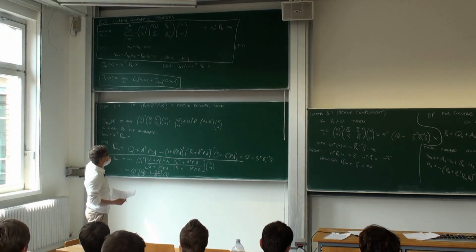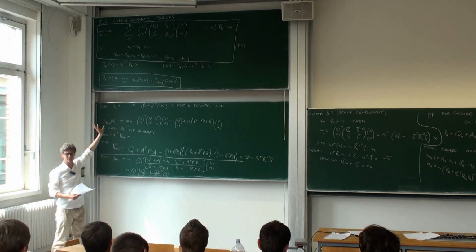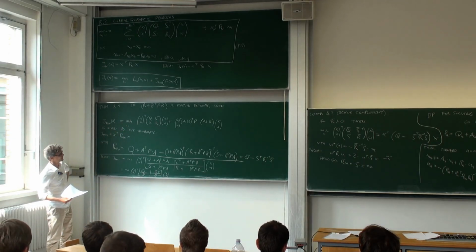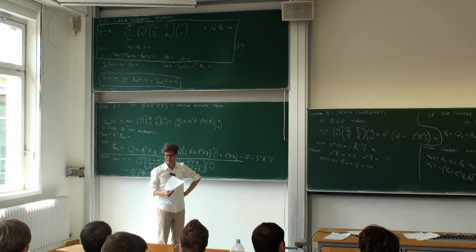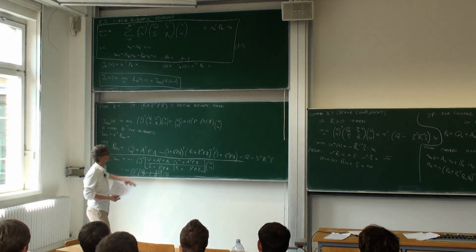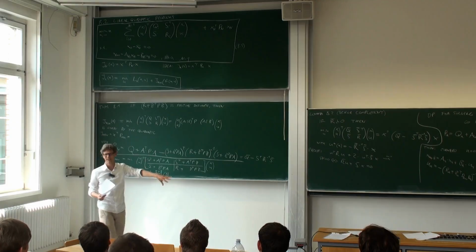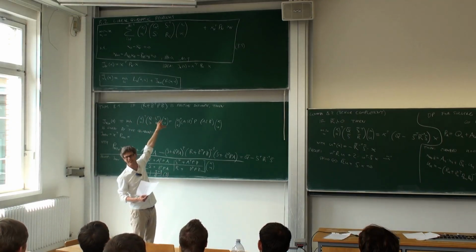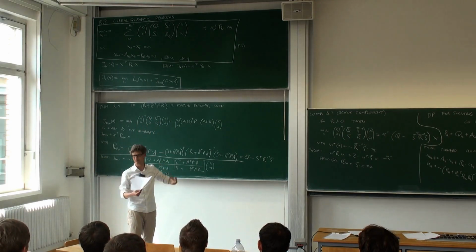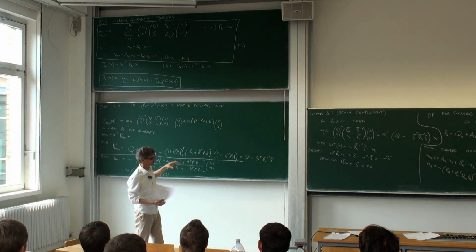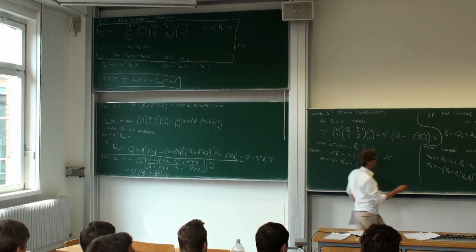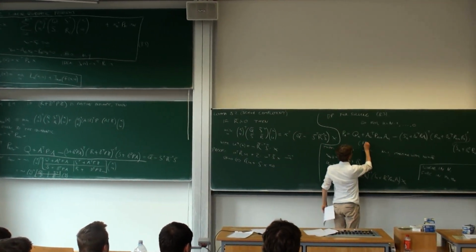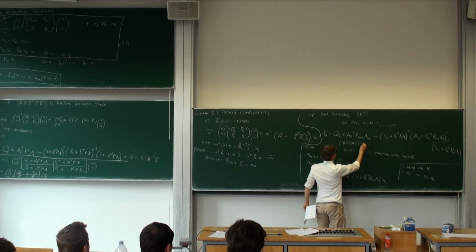There's also an option to add equality constraints. In some cases, you can incorporate them and still have the same representation. But in order to really deal with inequalities, in practice you do other things. You introduce them into the nonlinear problem. Then this one is the linearization of your nonlinear problem, and you're back at Newton type optimization. And you use the dynamic programming, or actually we call it Riccati recursion. This is actually the Riccati difference equation. I should give it the name. This is the Riccati difference equation.